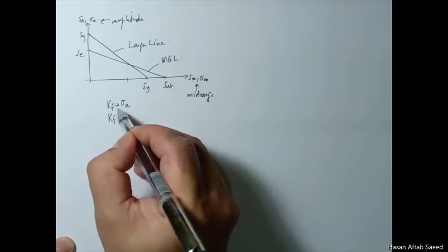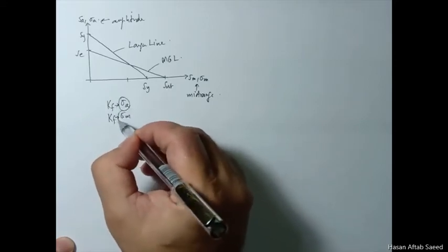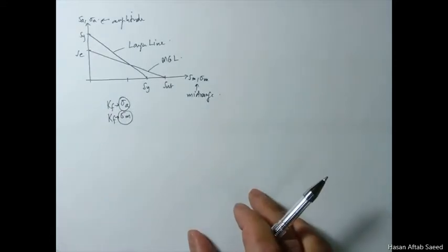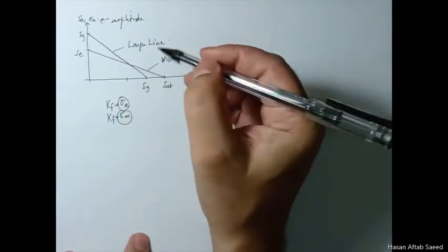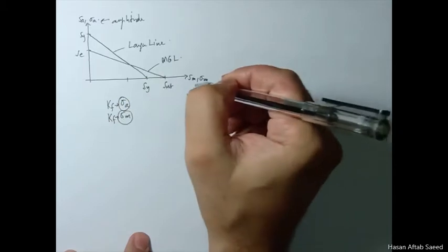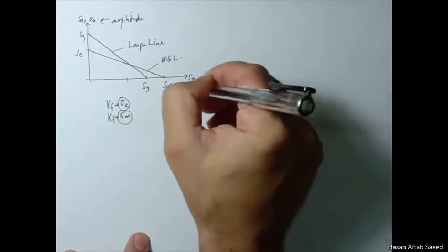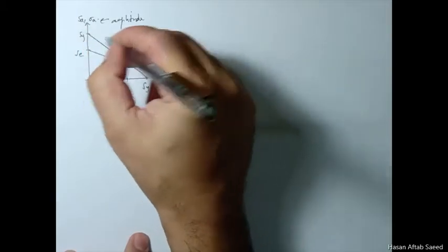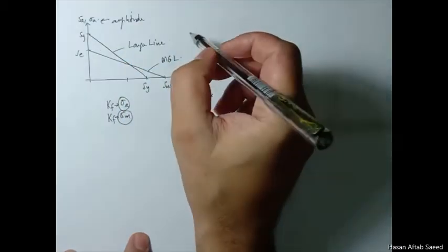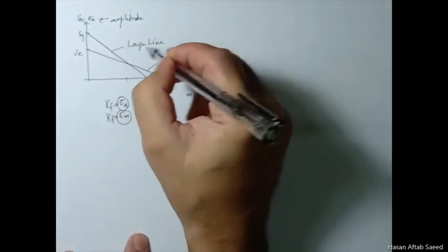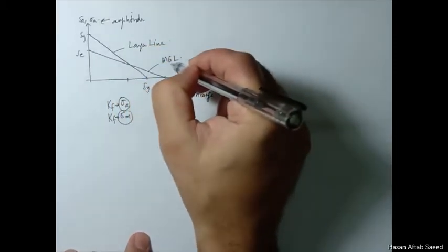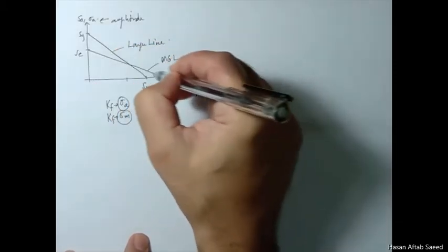You apply these to get these values, and essentially what we do is we plot these values on this fatigue diagram. This is the mid-range axis, this is the axis for the amplitude component of strength and stress both. So these lines are there. This is the Langer line, yield line, and this is the Modified Goodman line.